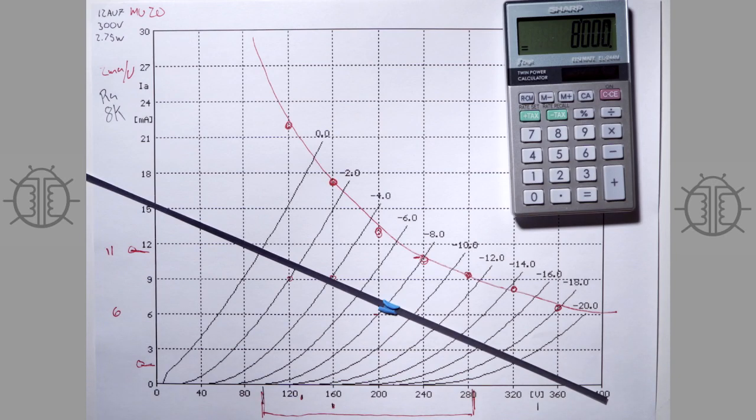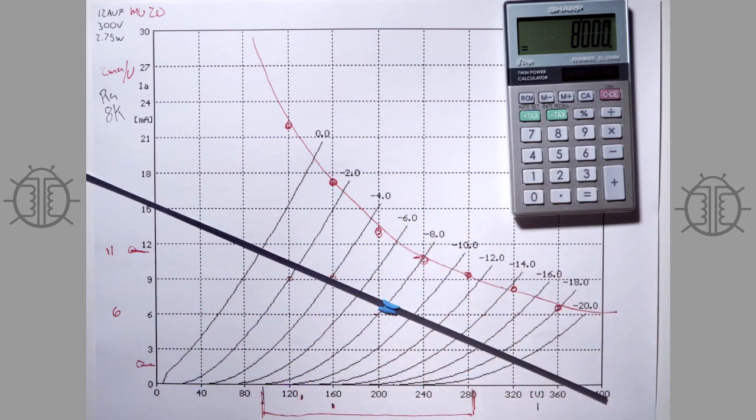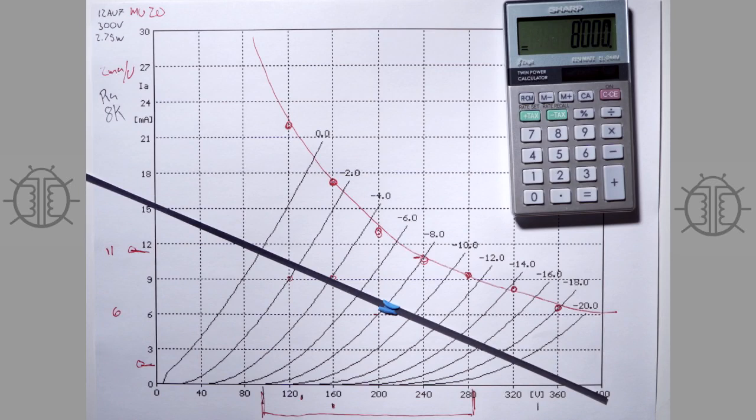And so we'll get to that because you can see that this triode is sort of halfway between what you would call a voltage source and a current source. The lines kind of just go through like this. And later on, we're going to look at a pentode when we do Class A, B load lines. And when we look at the pentode, you'll notice that the lines go up and then they come basically straight across. And so when you hear people say a pentode is like a current source or it has a very high plate impedance, this is what they're talking about. The question is, how much current do you have to put into the plate to change the plate by whatever voltage? So that is the question.